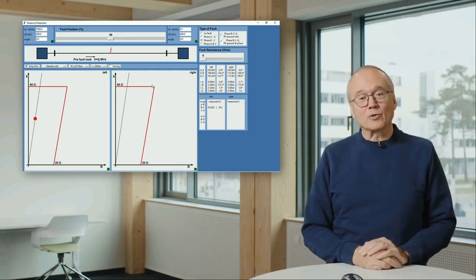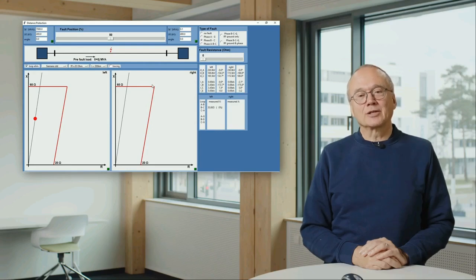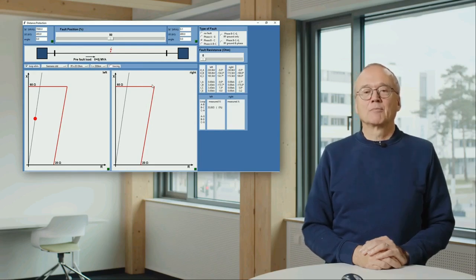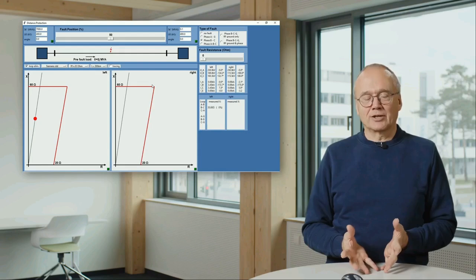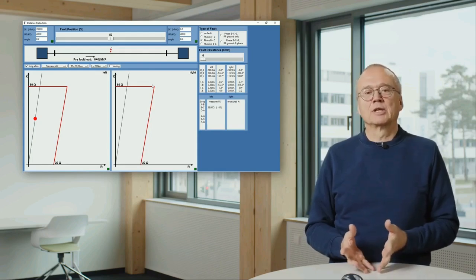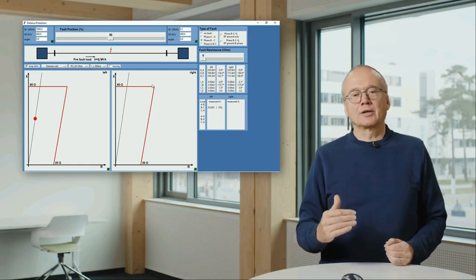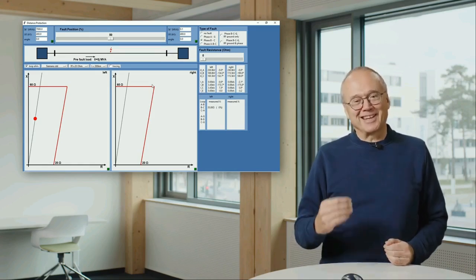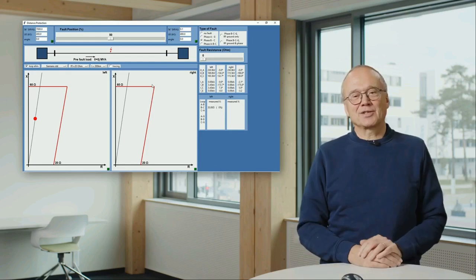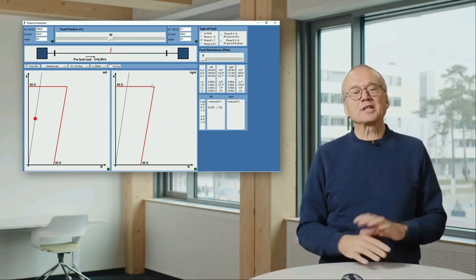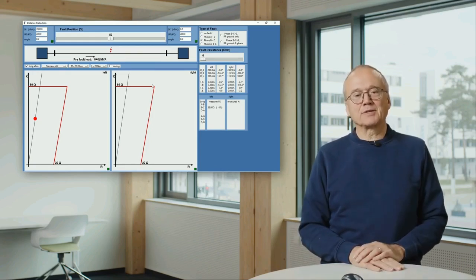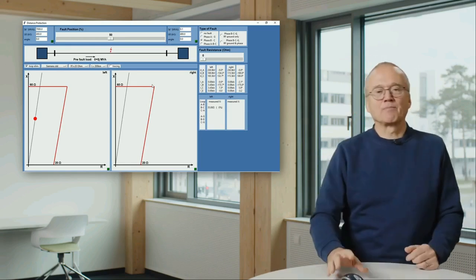And that is why the red dot on the right relay side is missing. Because if the relay doesn't see current, it cannot do the measurement. Every distance relay needs a certain minimum short circuit current to do the measurement. Again, that is a setting value which has normally a reasonable preset, so you don't have to change it.